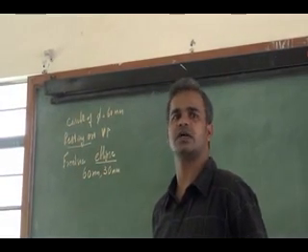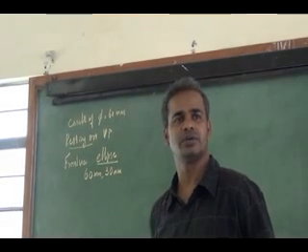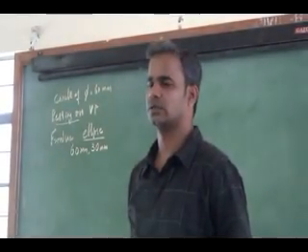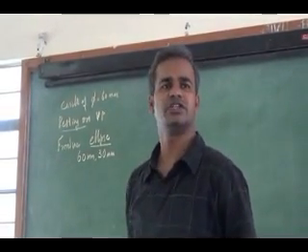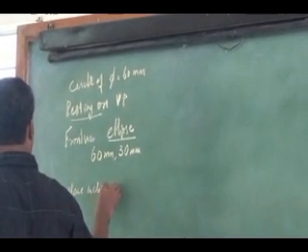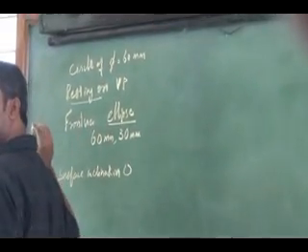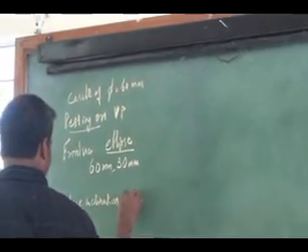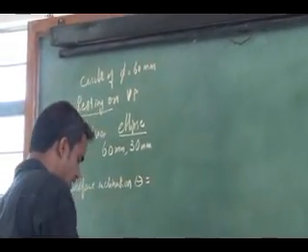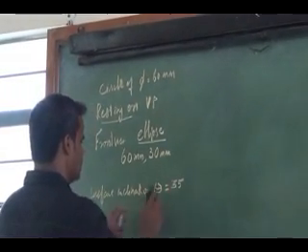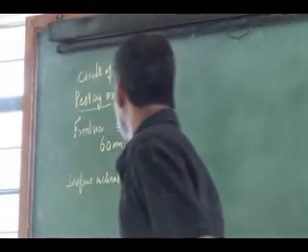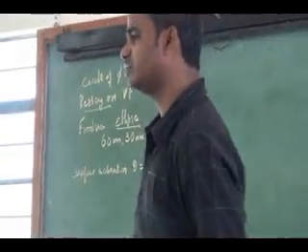If the surface of the lamina has an inclination of 35 degrees to HP, the surface inclination is given. HP inclination in the sense of surface inclination is a true inclination, it is theta. Theta is 35 degrees. Draw the projections of the lamina.